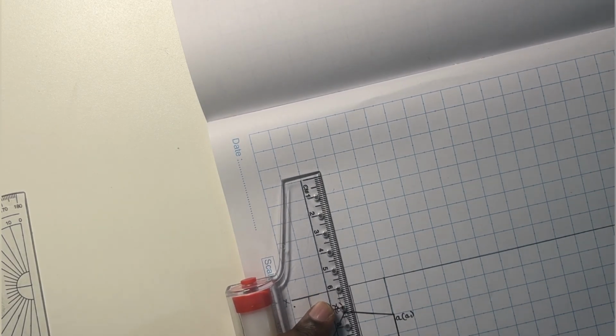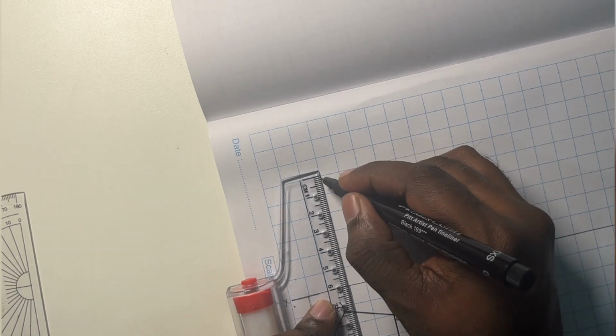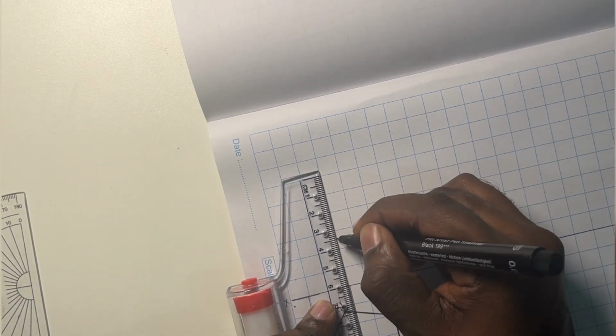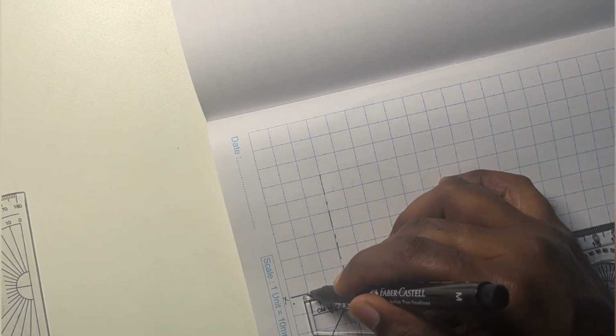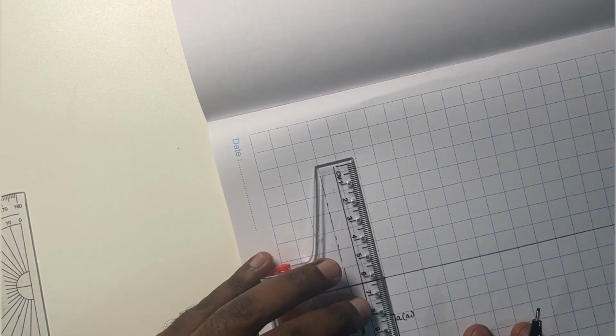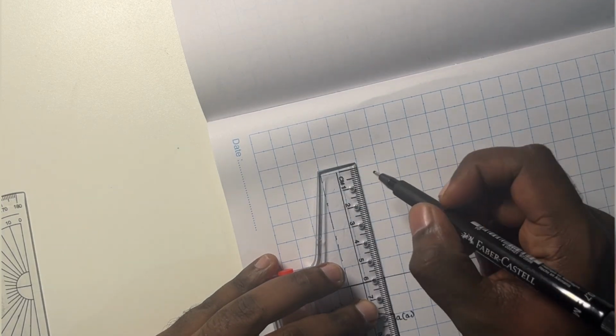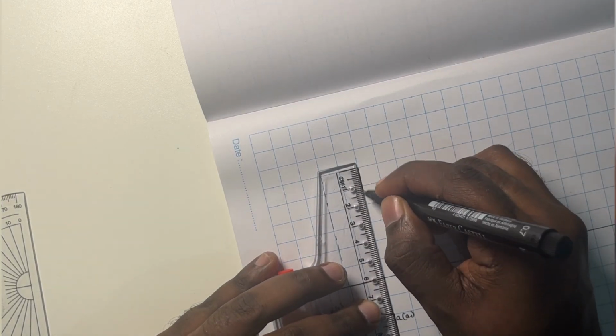So let me construct the 60 mm line in the front view, which marks the axis of the prism. So I'll be using the chain line for the construction. So this is the axis line. Now let me complete the prism front view. So first, by joining the extreme endpoints, I'll mark the base of the prism. And next, all the other corresponding edges will also measure 60 mm, that is 6 centimeters in length.